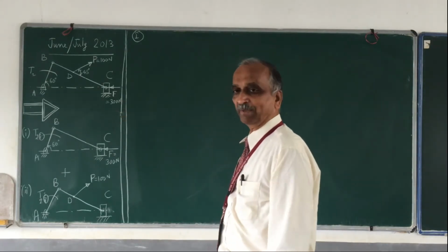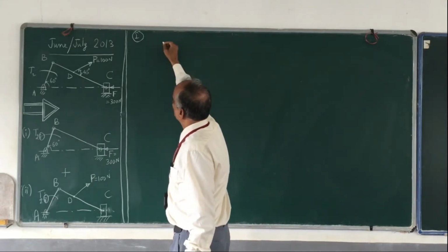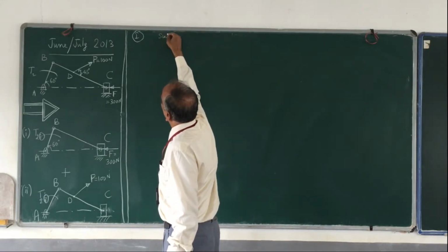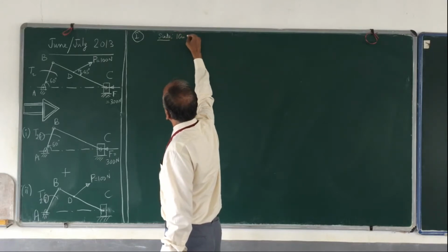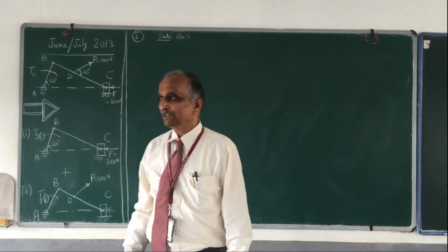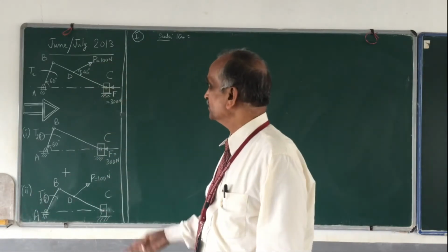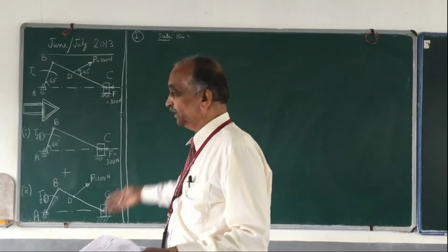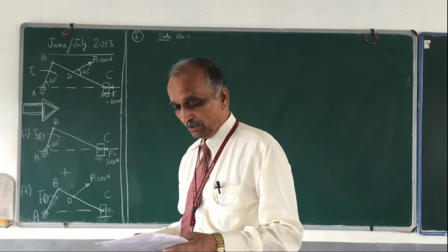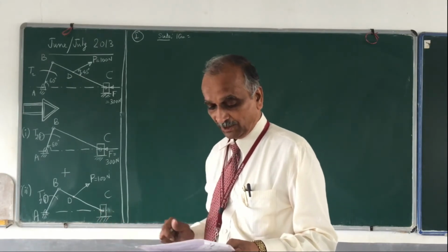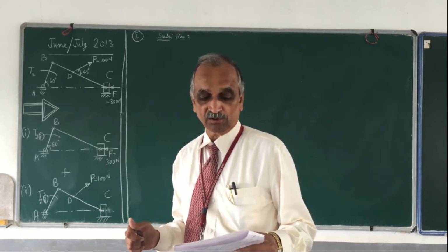Drawing the mechanism diagram to scale. First you choose what is called the scale. Scale is equal to, first thing you need to write, don't skip it, 1 centimeter of the drawing is equal to how many centimeters? What does it represent? To decide this, you go through the values. AB is 10 centimeters, BC is 70 centimeters, and BD is 25 centimeters.